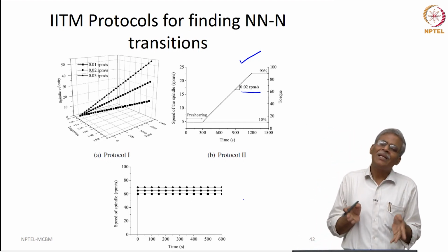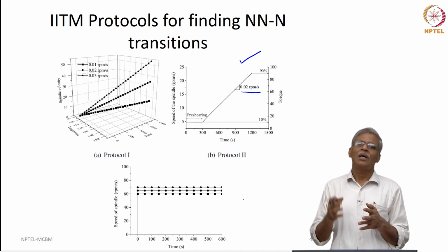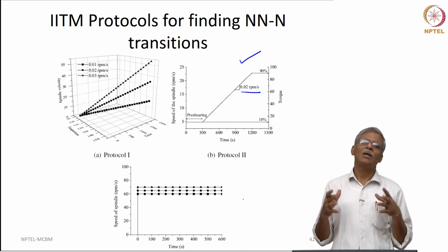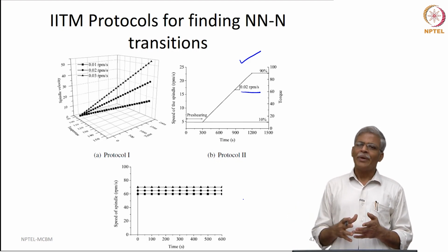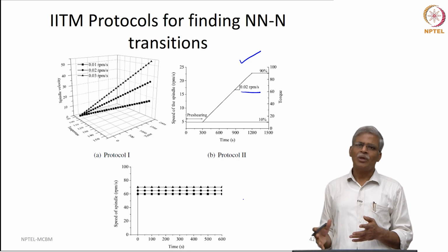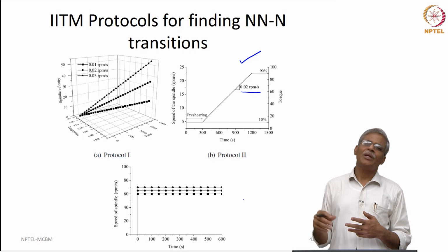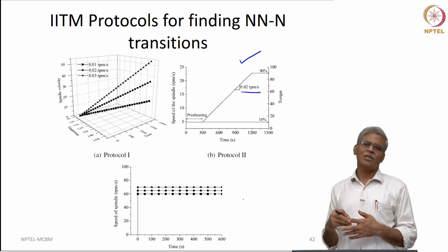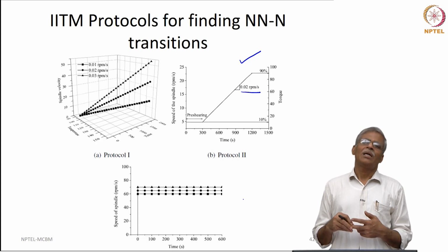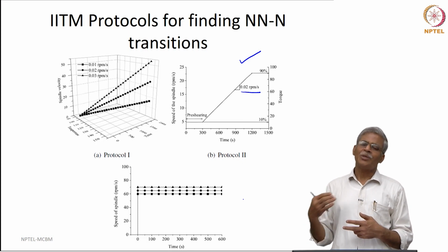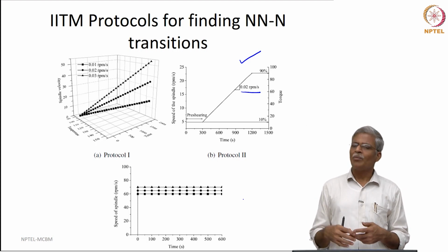But what really happens during the mixing, during the compaction process? As the mixture is dumped in the field and as it is subjected to compaction using your compaction rollers, many things happen. One is the temperature of the mat substantially starts reducing, that is number 1. Number 2 is the mixture is being subjected to a substantially high amount of shearing due to the roller compaction.